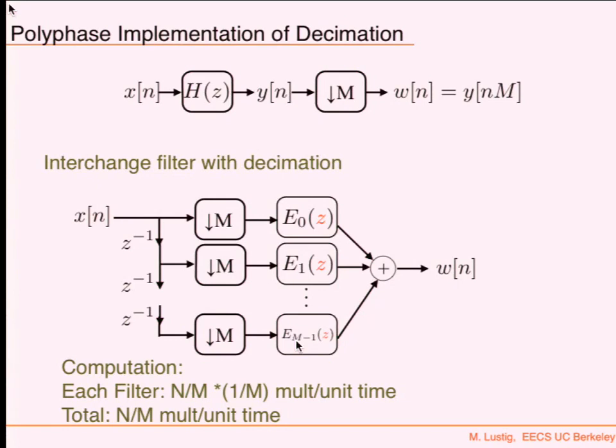That's the whole idea. The whole idea here is to find a formal way of decomposing a filter such that you don't compute whatever you don't need to compute. If you open GNU Radio Companion, there's a built-in block that implements a polyphase filter because it's very efficient. And what it does, it filters and downsamples. Okay, so it's a polyphase filter downsample.